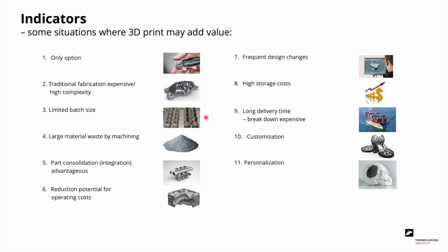The batch size is limited. We are not talking millions of parts. We are talking tens, hundreds or thousands or even tens of thousands of parts with the present level of 3D print technology. If you by traditional fabrication have large material waste, it may be worth considering 3D print. If it makes sense to consolidate parts, integrate them into one piece, it may make sense.